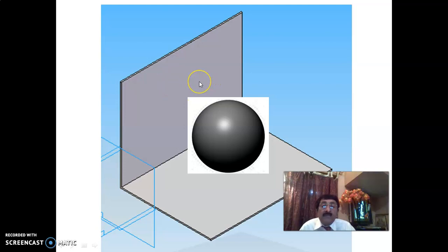That is why whenever a sphere or hemisphere comes, you have to be careful. In isometric projection, you have to do the isometric projection only. You can't do the isometric view. So far, the isometric view would have been enough because complications were not there. Whether it is isometric view or projection, the view used to remain the same. That is why if they say isometric view, you don't have to change the scale. If isometric projection, you take the scale. Both are similar, but the only thing is the size will change.